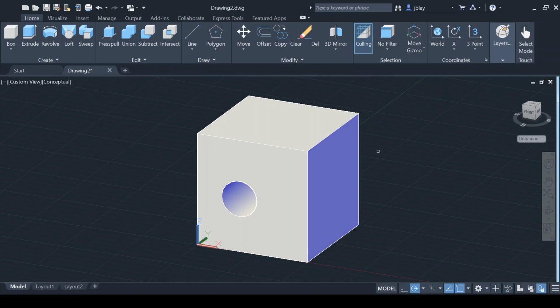Now let's say I wanted to cut the top off of this. I would draw a triangle here. Make sure I'm drawing on the front if that's what I want to cut away. Make sure that it's hovering blue on the front view. Let's say I want to draw a triangle like this, making sure everything is on that face that you're intending to intrude along.